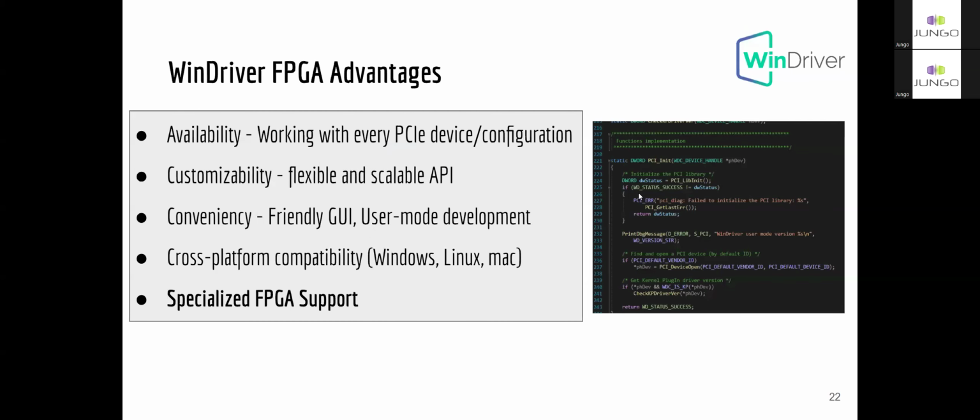So we know that manufacturers, AMD, Lattice, Altera, Intel, provide a default driver for the XDMA design or QDMA design or BMD design. So why use WinDriver? The first one is the availability. The first advantage, we are working with every PCIe device or configuration. So if you're working, for example, or testing several FPGAs, you can use WinDriver and use the same code and same function names and so on.